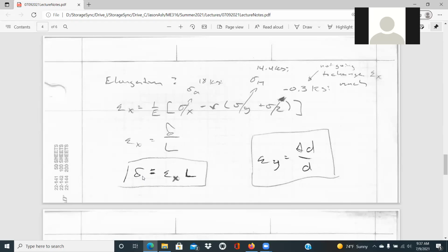And I've mentioned before, the pressure vessels running from the powerhouse for the hospital to the hospital have these long pipes interconnecting, but then they have flexible couplings at the ends of those long pipe segments, just to allow free expansion and contraction of the pipes as they are subjected to pressure changes and temperature changes, so that you don't build up a stress in the X direction. The strain in the X is fully allowed, and that displacement would just be the strain times the length of that pipe.